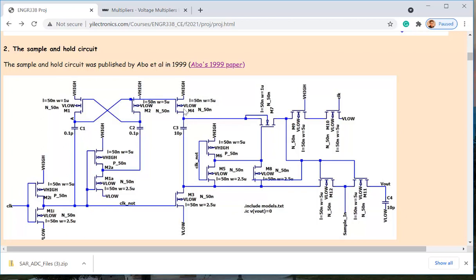Whenever it passes VDD to here, at the same time, this NMOS is on, so it's discharging the other side of the plate to ground. So which means it's like you have a voltage source on the top to dump charges to the cap here, and the other side is going to pull charges down to ground. So it's going to have a VDD voltage drop across the cap during that process.